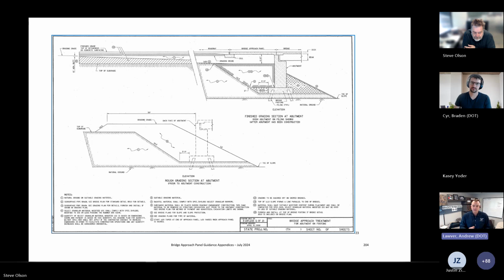The other thing that we put in there is a 28-day cure, because some of those chemicals and adhesives don't work very well when the concrete is curing. Those are some of the things that we've been doing in D7 to try and get a better product out of those E8 joint installations by our contractors. Does that help?